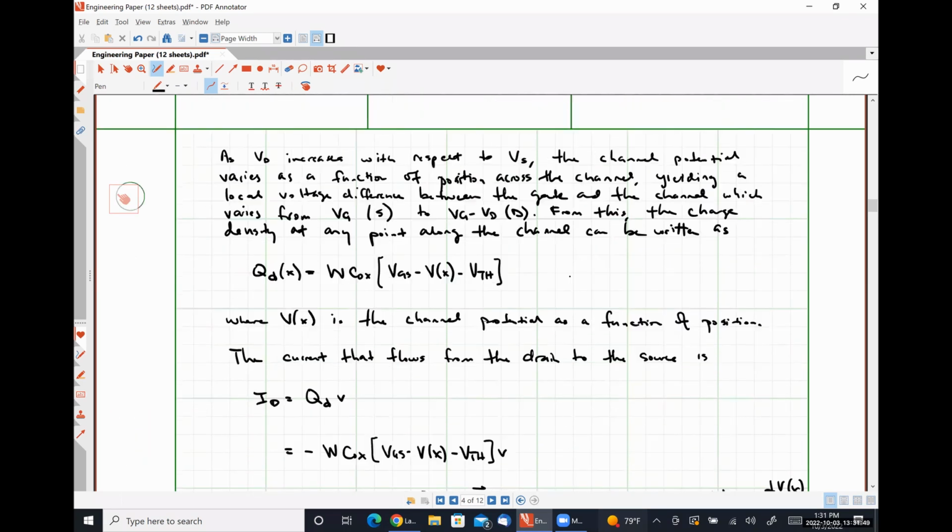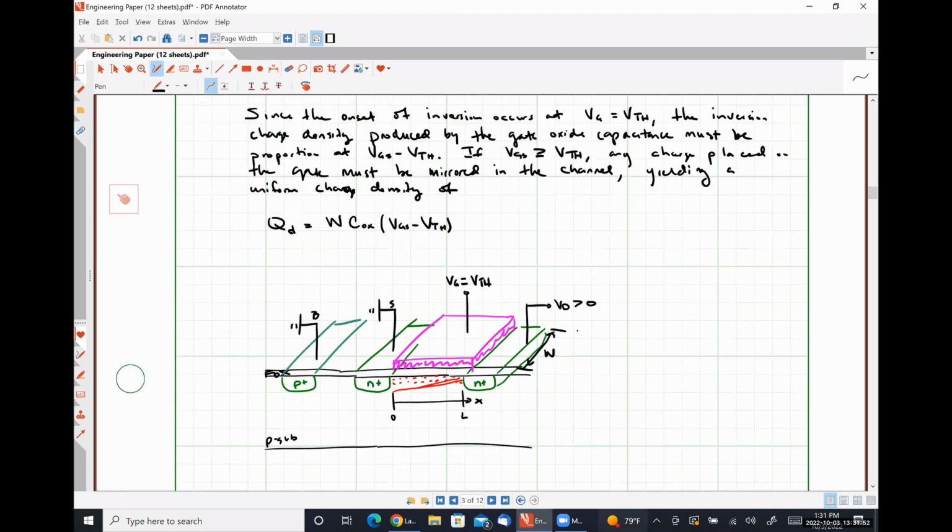And if we repeated this where our drain voltage was large, such that we pinched off our channel, we're skipping a couple of things here, but again, this is a review, right? So let's talk about this number right here. Here we are assuming that V_D is greater than 0, but also that V_D is less than V_G, and we get this nice line. Once V_D exceeds V_G, we have something that looks like this, very, very exaggerated, but effectively our channel becomes pinched off.